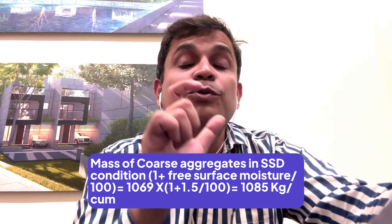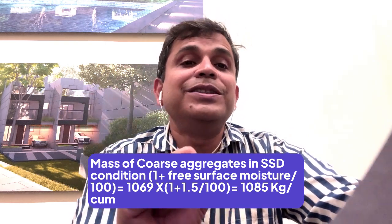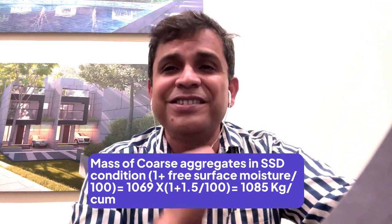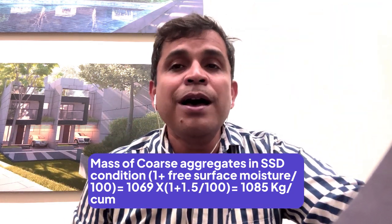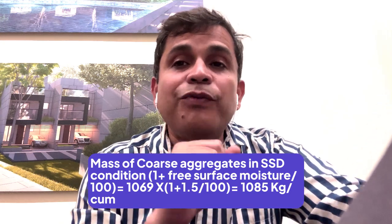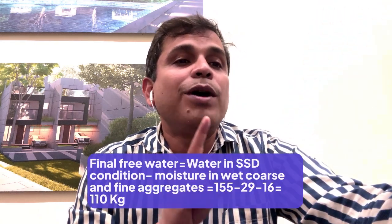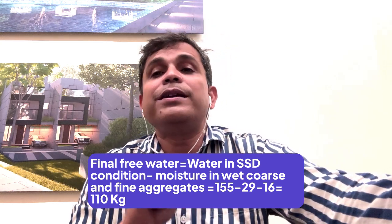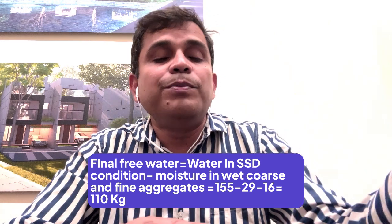But 1085 minus 1069, this 16 kgs, what is this? That is moisture, and that will be added into the mix. So from the fine aggregate we are getting 29 kgs, from the coarse aggregate we are getting 16 kgs. So in total how much are we getting? 29 plus 16, that is 45 kgs. Now what is my total water in the mix? That is 155 kgs.